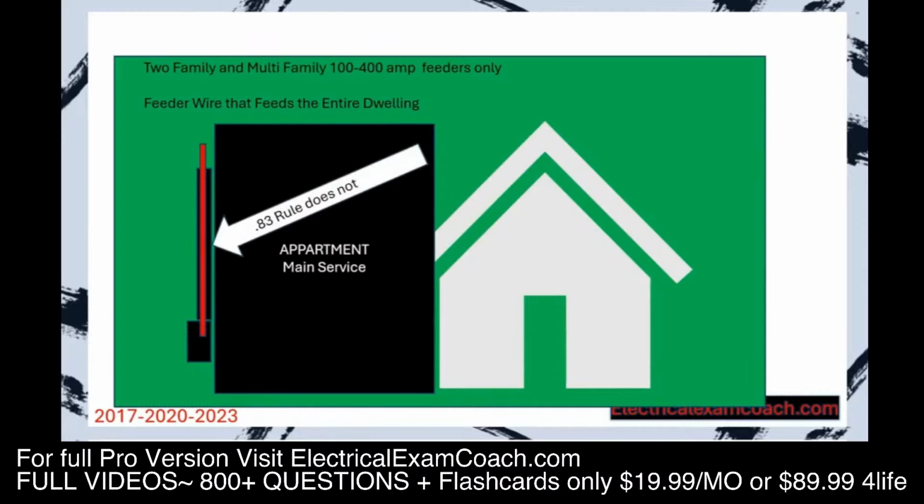You're going to use all of the previous rules that we learned before and apply those. But the individual feeder going into that unit does. The 83% rule does apply. And the beauty of this is it allows you to save money in the long run. Whether you're doing single family dwellings only or you're doing the individual units of the apartments, you're going to be able to use a smaller wire based off that table than you would if you sized it like normal. And over a year's time, that could save you a lot of money. So that is when the 83% rule does and does not apply.